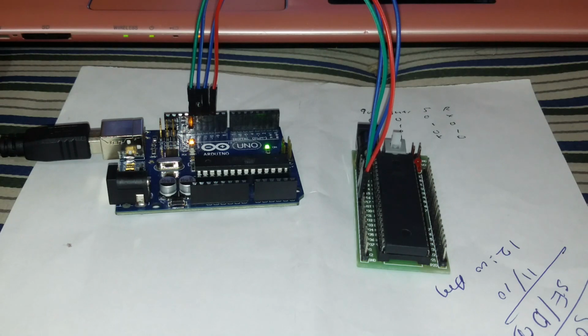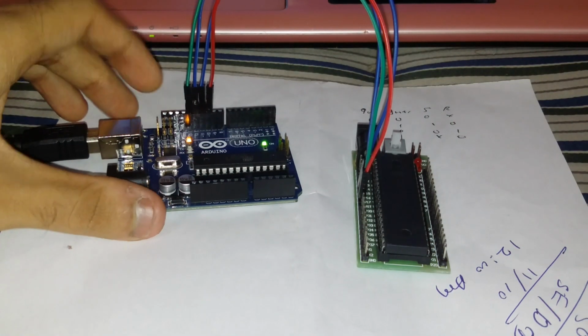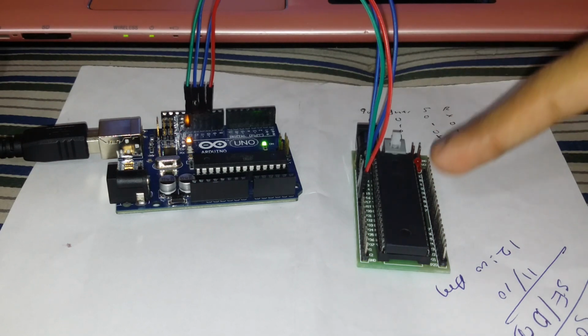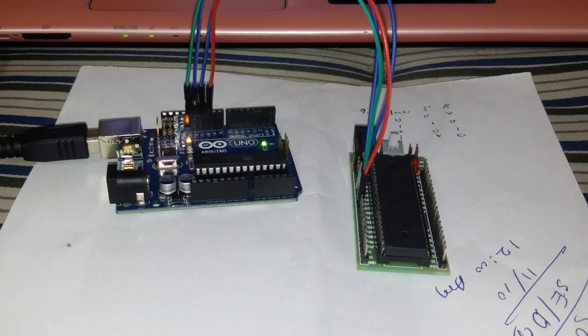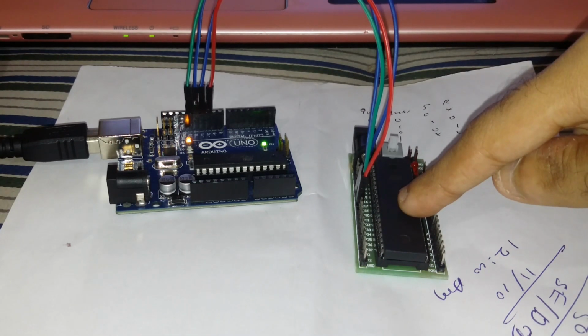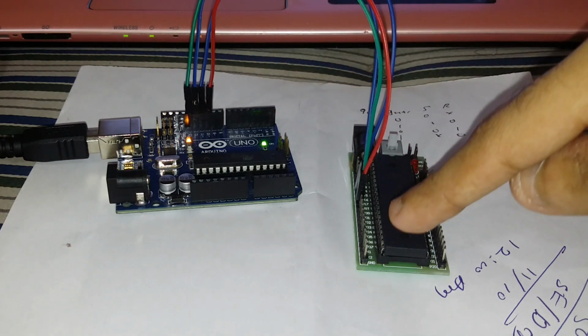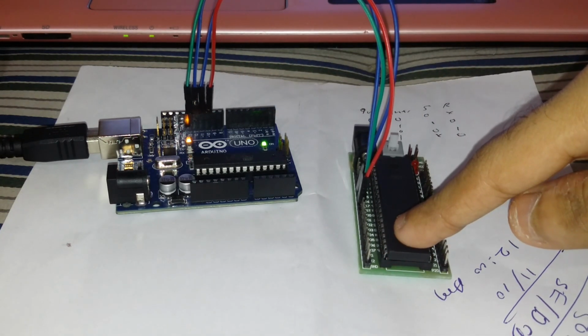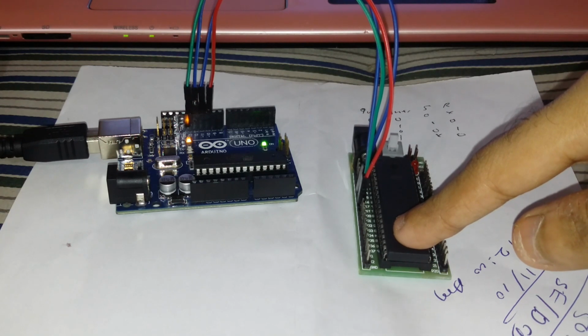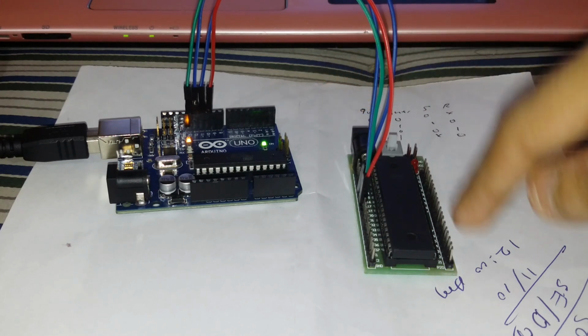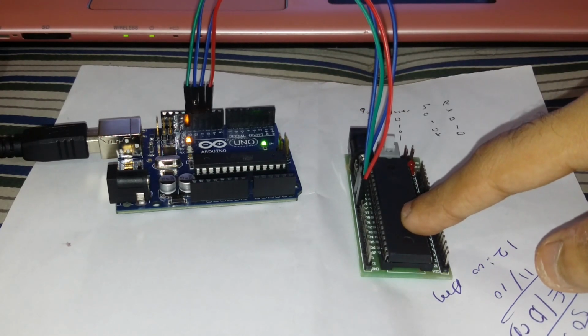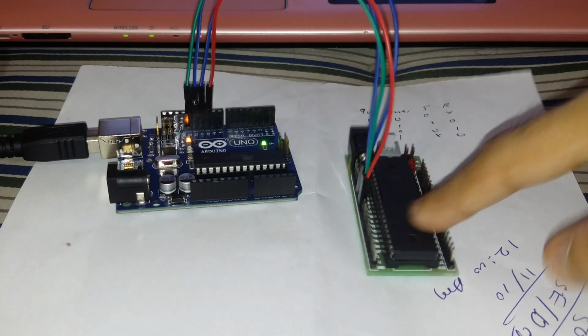Okay, so what I did was connect pin number 11 of the Arduino with pin number 6 of the microcontroller, that is port 1.5. Then connect pin number 12 of the Arduino with pin number 7 of the microcontroller, pin number 13 of the Arduino with pin number 8 of the microcontroller, and pin number 10 of the Arduino with pin number 9, that is the reset of this microcontroller chip. Alright, so now take another wire,